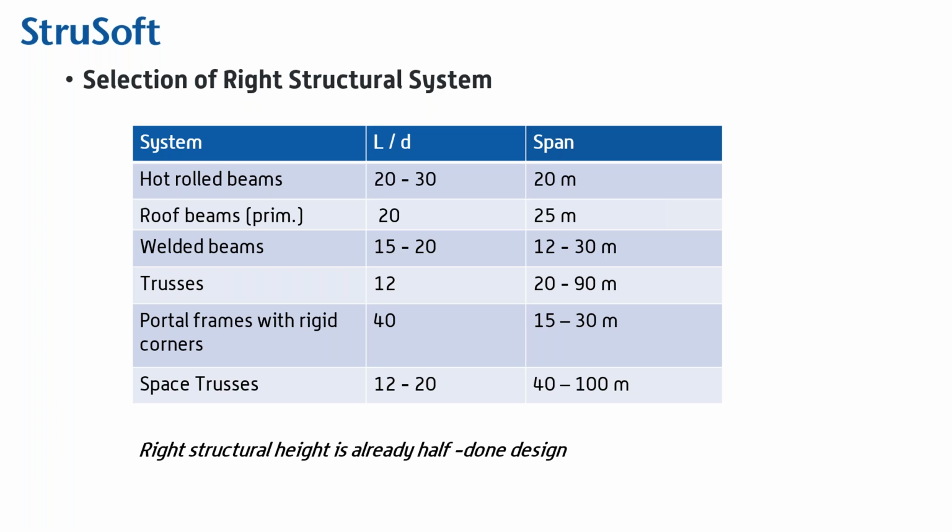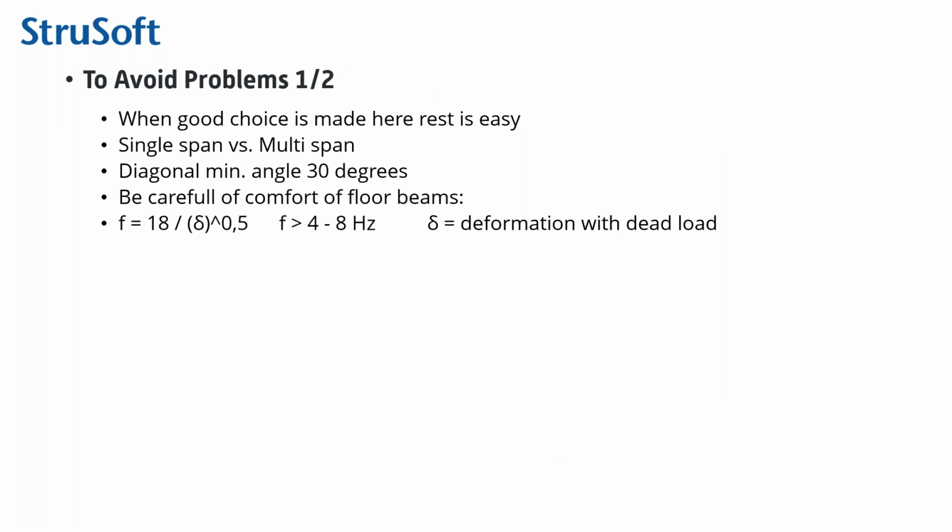You have a lot of elements in a small space, so you can get more slender structures. So if you stick to these rules, it's easy to design your truss connections and all the stiffening elements of your structure. Of course, these are not fully fixed rules. If you don't obey these, okay, you can go along, but you will eventually run into some problems later.